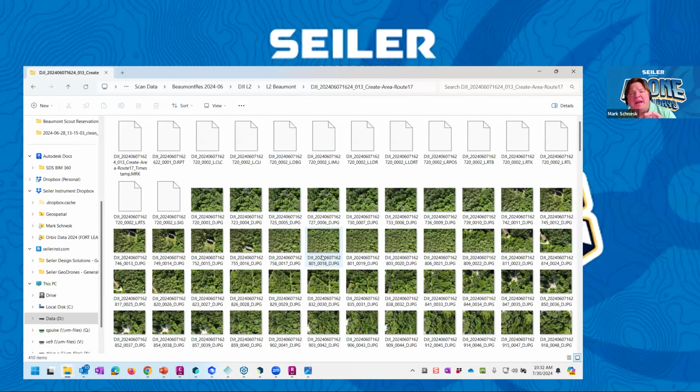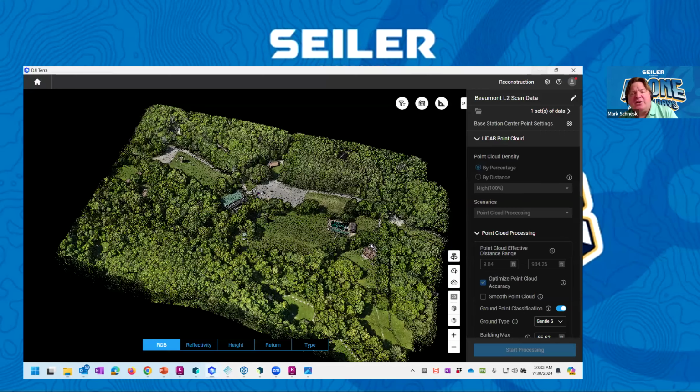But we can view these point clouds in a variety of ways. One of the other things that we get from LiDAR that we do not get from photogrammetry is intensity. As the LiDAR ray goes out, it bounces off an object, and a certain percentage of that energy comes back to the sensor, and different materials are going to bounce back different amounts of light, so we can view these LiDAR scans in different intensity values. You're also going to get the actual IMU data. The DJI L2 requires an RTK, or we can also post-process this. Other systems like the Wingtra GeoCue require a static base station logging data on site, or I could use something like CORS data or a virtual reference network OBS file, but there's going to be post-processing of that trajectory involved.